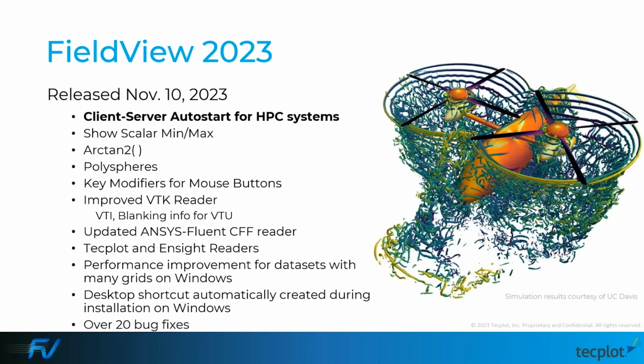So stay tuned. It could also be that some users aren't familiar with the feature detection type of things that we've done in the past, like the Q criterion and that sort of thing. So yeah, it could be that. We also have specific vortex flow features and a vortex detection panel where you can compute vortex scores. I encourage the user, if he's not familiar with it, to check our vortex score capability. It's going to connect through lines the core of all the vortices in your dataset. And then it's great for seeding a few streamlines and really highlighting the stronger recirculations in your flow.